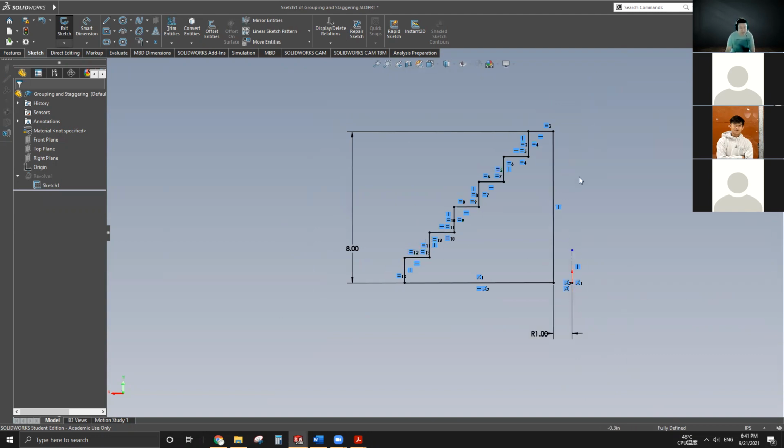After that, revolve it from a certain distance, which is 1 inch from the axis. So this center hole has a radius of 1 inch, and diameter-wise it's 2 inches, and the total is 8 inches tall.